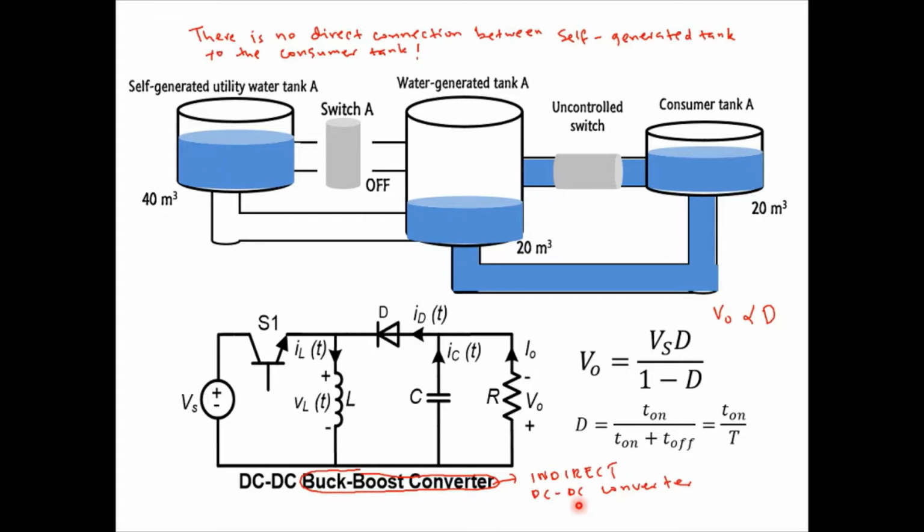However, similar to the previous converters, the duty cycle is always directly proportional to the demand. To perform the step-down function or buck operation, the duty cycle must be less than 0.5, and to perform the step-up or boost operation, the duty cycle of the converter must be higher than 0.5.